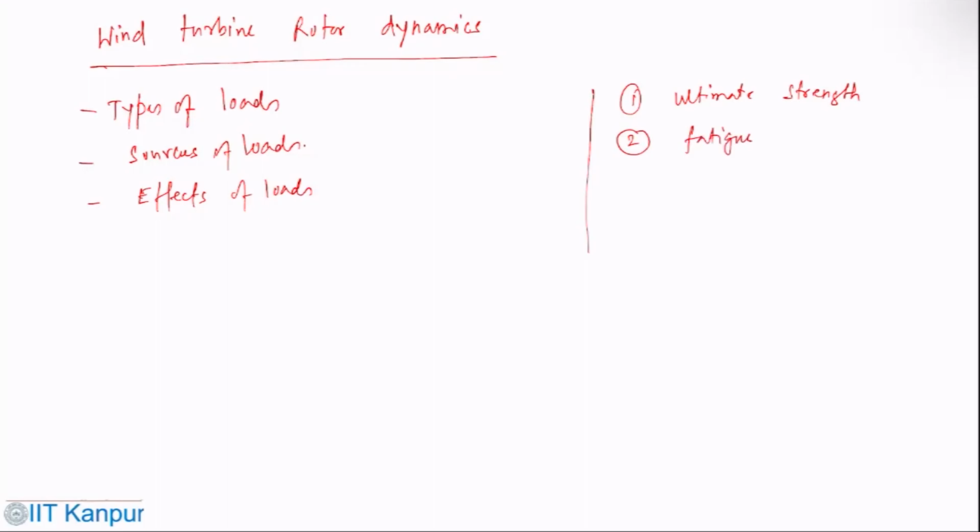Wind turbines sometimes experience very high loads, and they must be able to withstand those loads. Typical normal operation is accompanied by widely varying load due to starting, stopping, yawing, or passage of blades through continuously changing winds. But those are normal. These varying loads can cause fatigue damage in components, and sometimes that component may eventually fail at a much lower load than it would have when new.